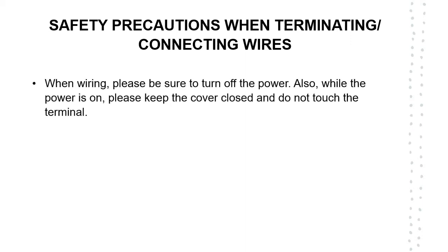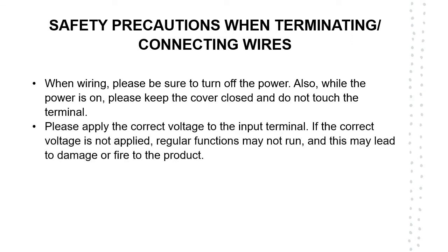And let us not forget the safety precautions when terminating or connecting wires. When wiring, please be sure to turn off the power. Also, while the power is on, please keep the cover closed and do not touch the terminal. Please apply the correct voltage to the input terminal. If the correct voltage is not applied, regular functions may not run, and this may lead to damage or fire to the product.